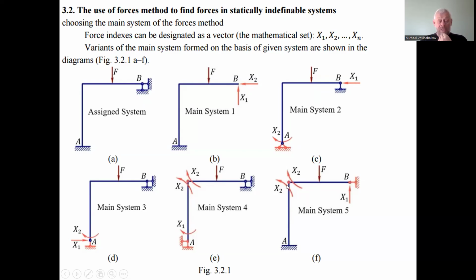When we have three hinges on a straight line, even very small gaps in the hinges, for example, can cause the displacement of the point B due to the property of the hinges located on the same straight line. So this is an instantly changeable mechanical system. So it can move here for much more displacement than the gap in the hinges 1, 2, 3.